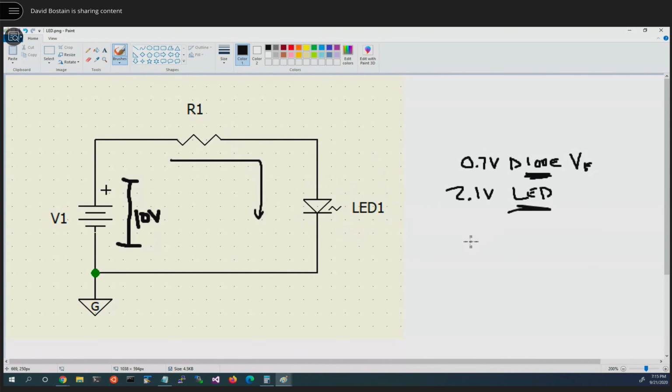But for an LED, we've been told that we have between 15 milliamps up to 25 milliamps as desirable values. 15 being when it's bright enough to see, 25 being when it's ready to be burned up. It's actually a little safety factor in here if we had real LEDs, but we're going to make it safer by picking a good range and then working here with 20 milliamps.